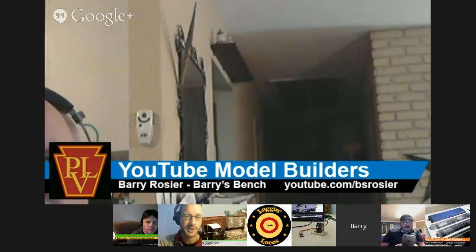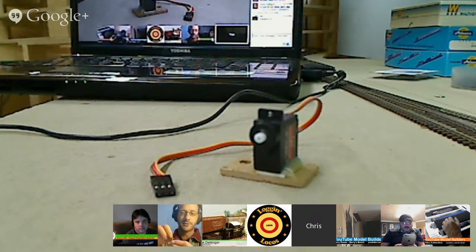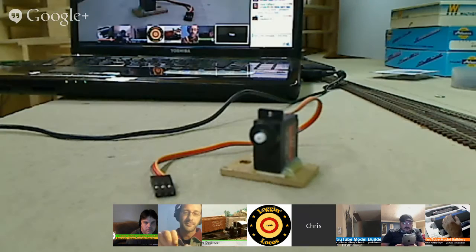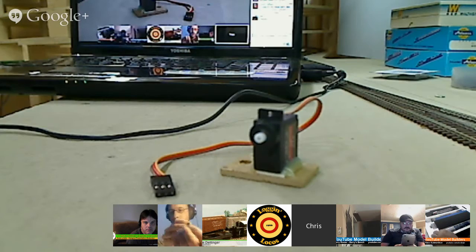The nice thing is if the servo has the wrong polarity or the wires are in a different order than the extension, you can pull those little metal pieces out of the plastic part and just change the position and push them back in. There's a little black tab in there. You pick it up with the tip of your X-Acto blade, and pull those pins out. The tabs can be pulled up.